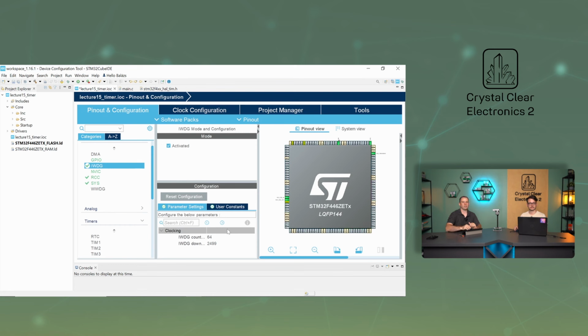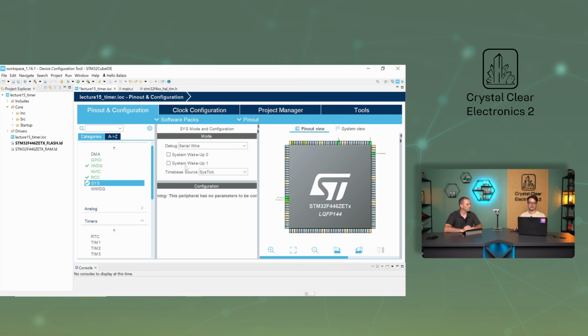In the case of Watchdog, we have limited options for prescaler. For this peripheral, we do not have to take care to set the prescaler value to 1 less, but we do have to pay attention to it when setting the counting limit. Set up the debug interface, then save your changes and generate your code.